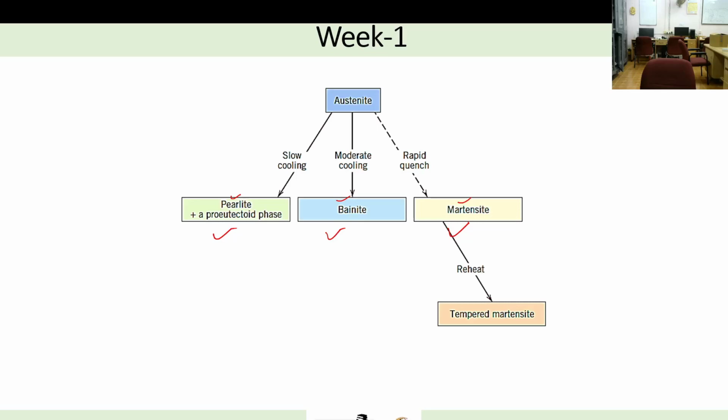When you finish the welding, that high temperature meets ambient conditions. That temperature difference will give you a very high cooling rate, if you are not using any technique to slow down the cooling rate.